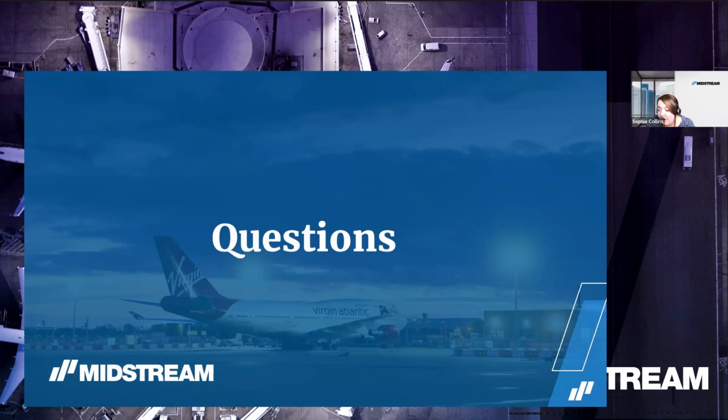Great, thank you. Our next question is, how do you estimate dirt conditions properly? The dirt conditions are estimated by the IESNA Recommended Practice 8, and divided into very clean, moderate, dirty, and very dirty. There are parameters like how many micrograms per cubic meter of dirt is moved, but we all know this is very nice to write on paper, but nobody knows how many milligrams of dust is moved in a certain place.